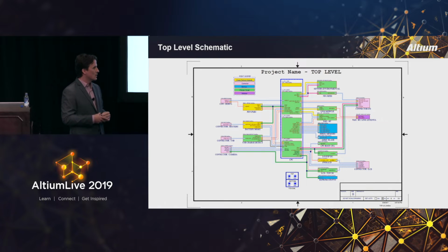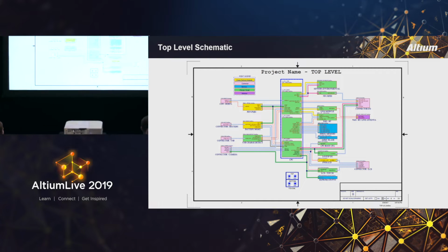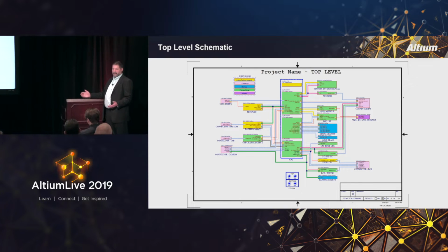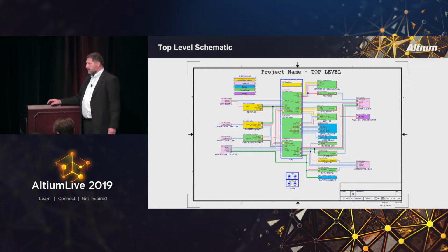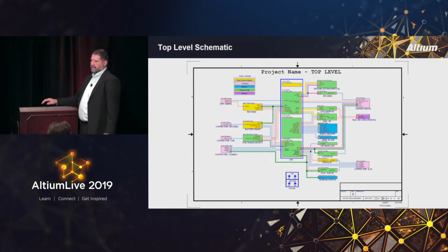In my experience, connector protection, ESD protection, is one of the most neglected or forgotten areas in PCB design. It's definitely one of the areas where a lot of mistakes for second pass designs are made. So by putting a lot of emphasis on that with a separate page for the connector, it really helps Max ensure that he's got good, adequate ESD protection and EMI protection for those connectors.